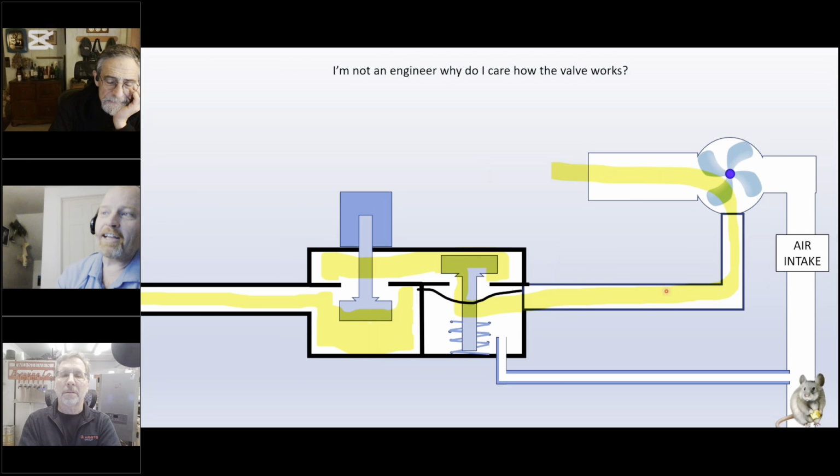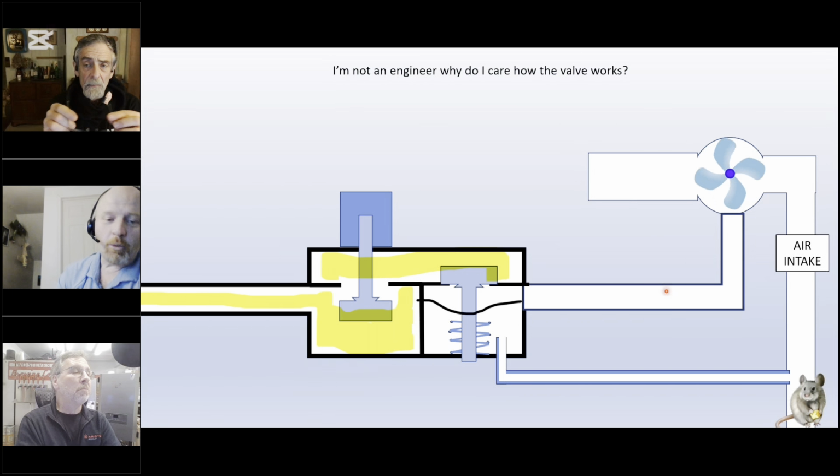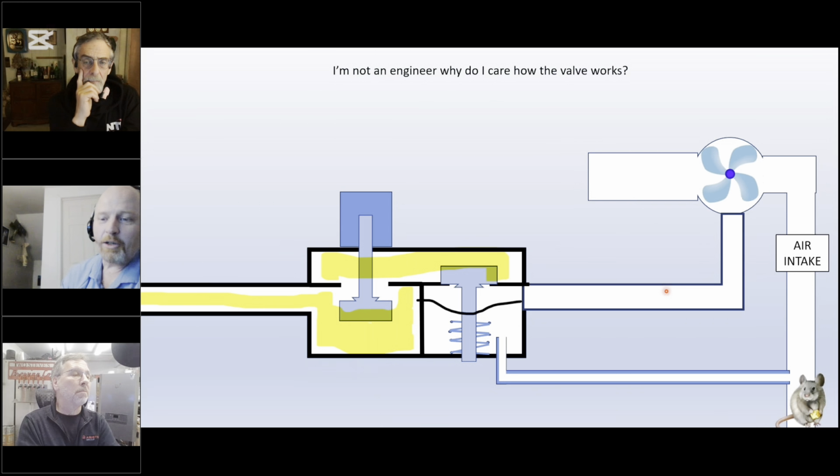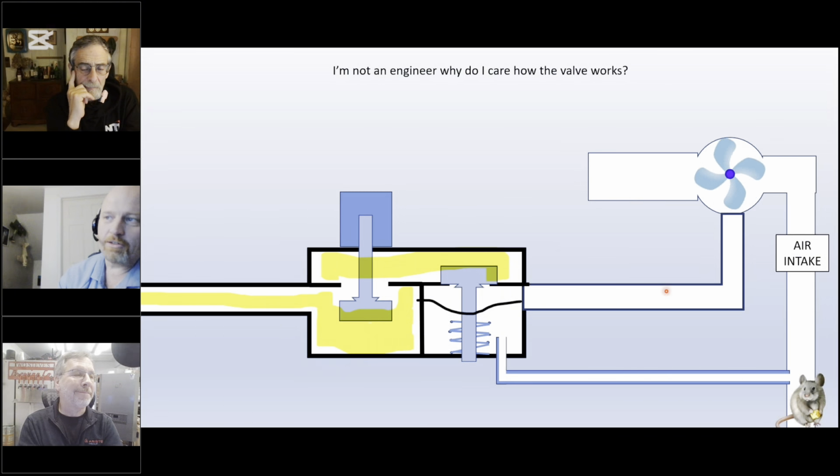You might not get a fan error, you might not get any other error, but what will happen is your boiler just fails to ignite or can no longer stay lit because there's not enough gas to support combustion.